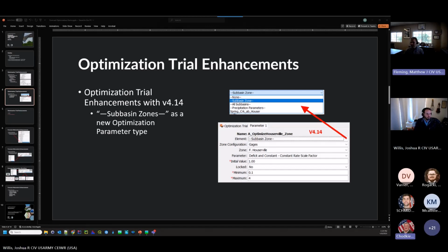So my guess, I'll just throw it out there. There's a layer cake of importance here. You have your base parameters in the basin model. That's at the bottom of the stack. The next thing that overwrites those is what's in the zonal editors, right? So your zonal overrides. If you have a zonal override for initial base flow, then that will win.